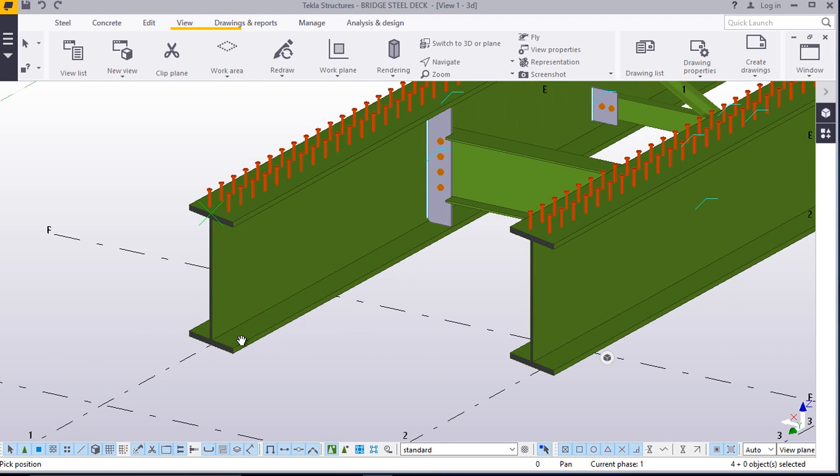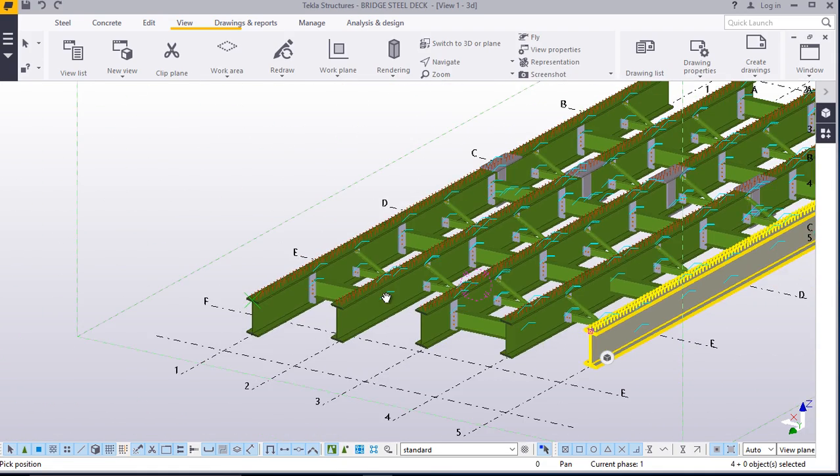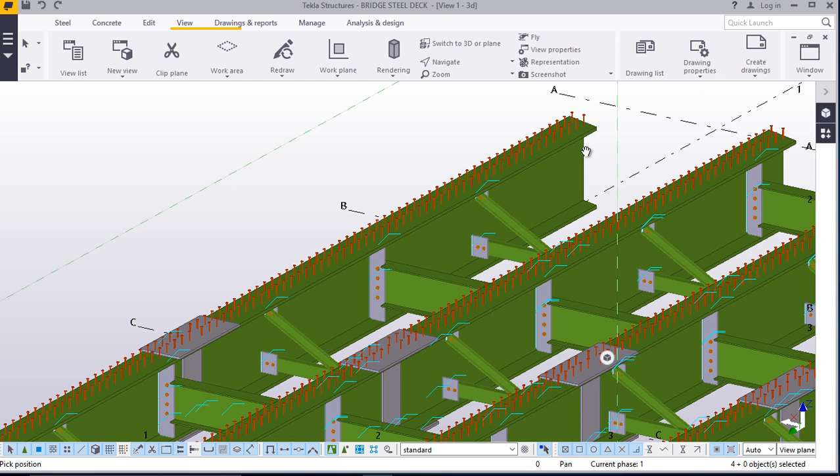Fixed end will be bolted and fixed completely on a grouting, and the other side will be sliding on a bearing, elastomeric bearing.